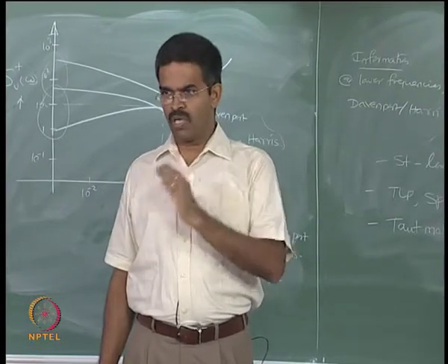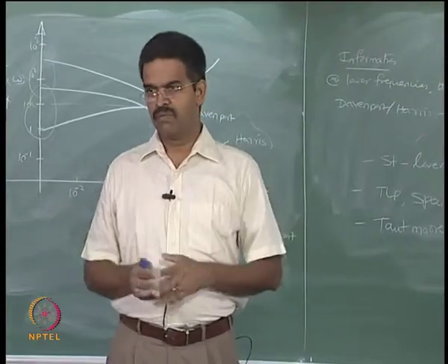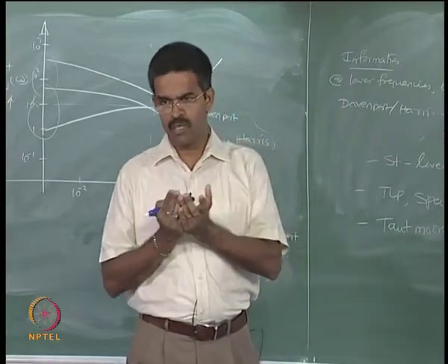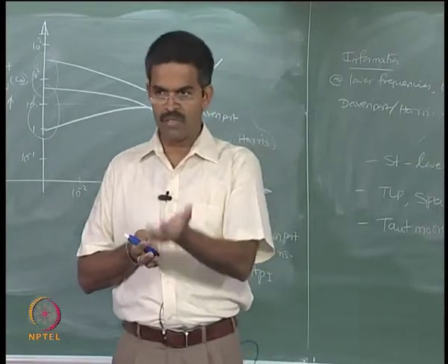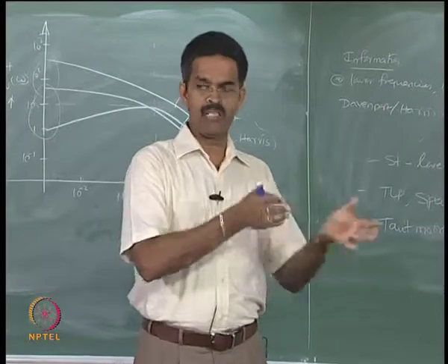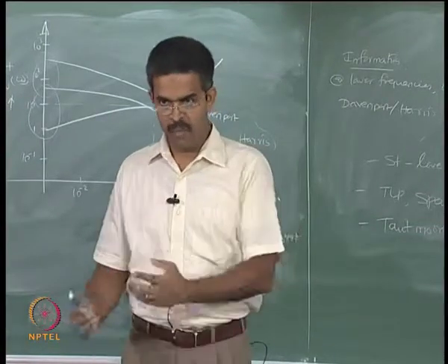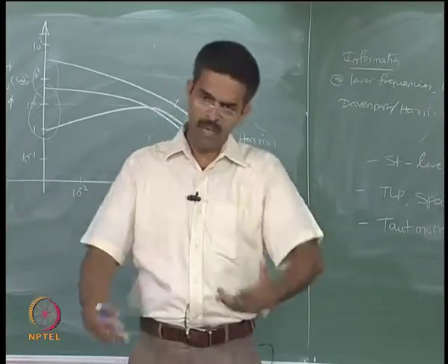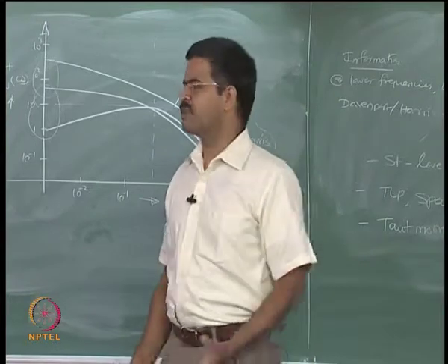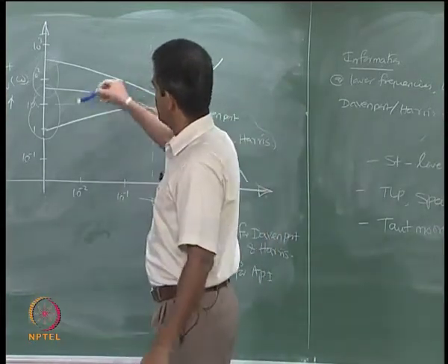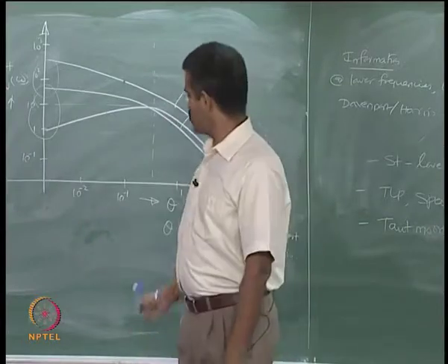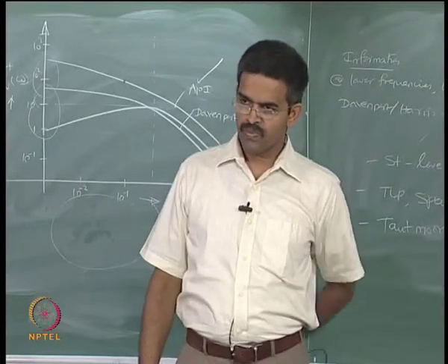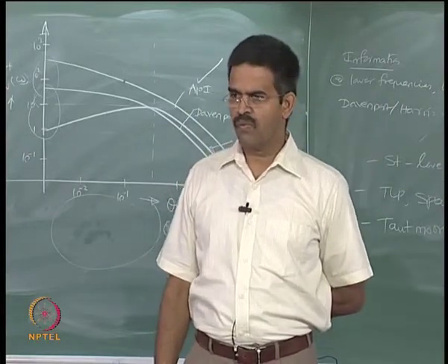Then we moved on to aerodynamic loading. We started with understanding the aerodynamic behavior on different classes of structures. The aerodynamic aspect is divided in two parts. One, the way in which you model the loading itself is a problem. Two, where you want to apply this load, to a fixed structure or a flexible structure, is also a problem, or it is varying. So we must specify very clearly which spectrum to apply for different kinds, because certain spectrums show significant variations in the low frequency bands, and those are the structures which are highly aerodynamically sensitive. Okay, so we have understood this.